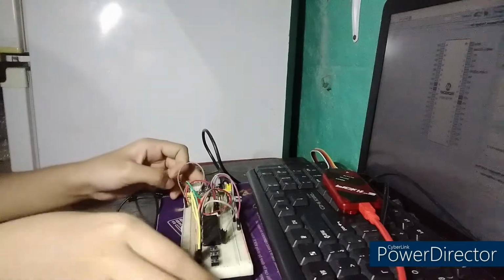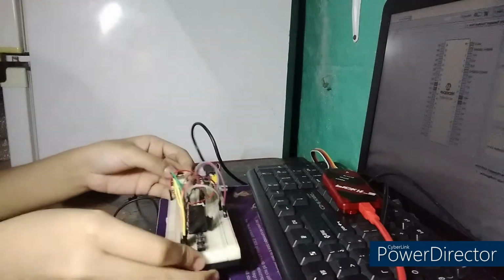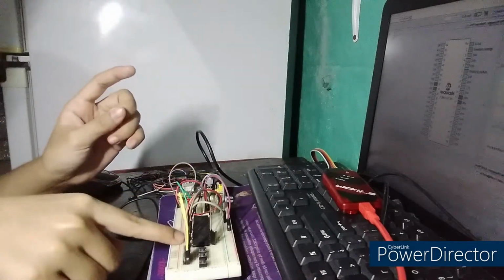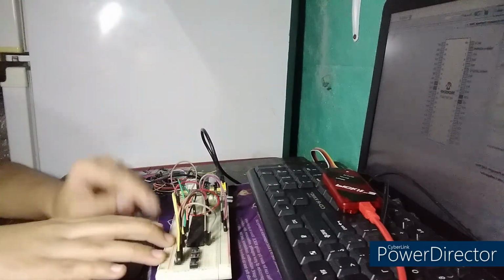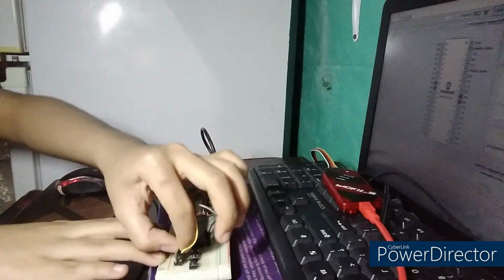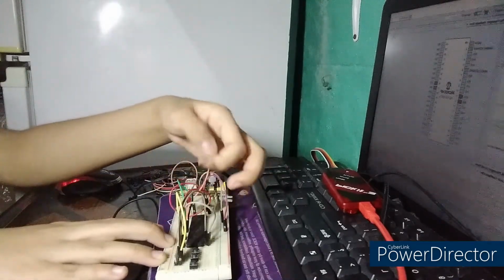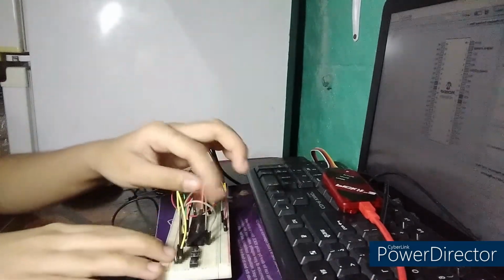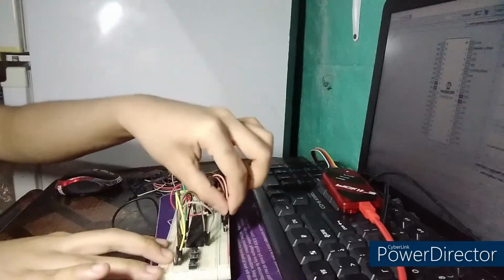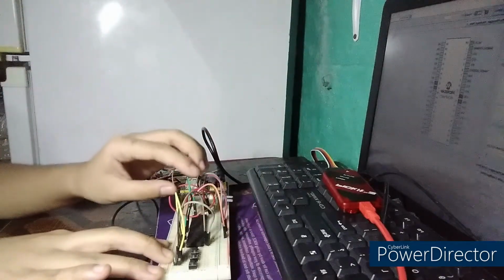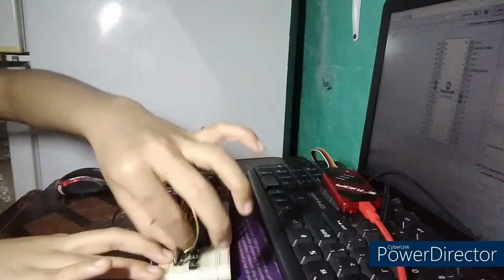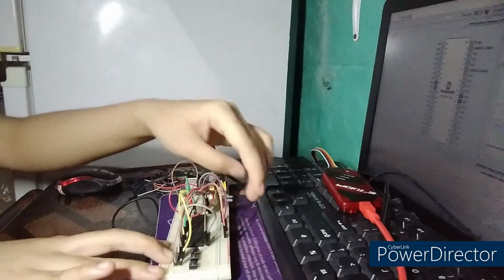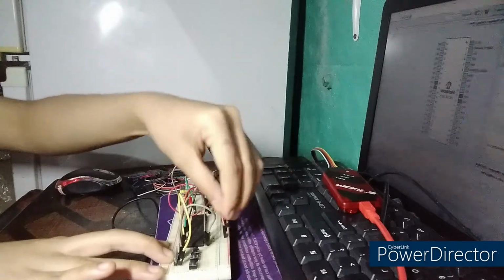And after that, do not forget the proper connection of our VDD and VSS. So our orange white wire here is our connection for our VDD. This will be on our positive terminal. Let's put it here. And then our VSS, which is on the 12th slot, this black wire here should be connected to our ground. So let's connect it to the ground.